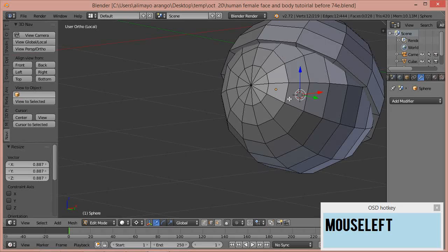Later on, we're going to put a subdivision surface on this eye. One of the things that a subdivision surface is good for is that it makes organic shapes look very smooth. One of the issues that pops up when dealing with subdivision surface is that if you have edges, it tends to make edges look non-sharp. So we want this edge of this eyelid to look sharp. There are many ways of dealing with that issue. One of the ways is just adding a loop cut next to an edge.